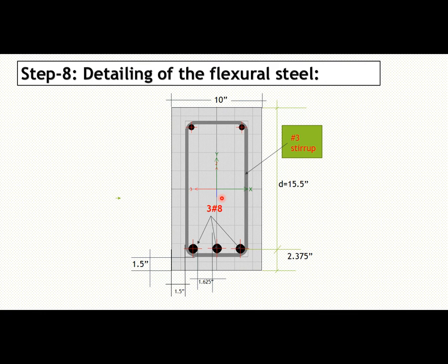Okay, if your beam becomes over reinforced, in an over reinforced beam section, the failure of the beam occurs by crushing of the concrete before yielding of the steel, which occurs suddenly, which is not expected. I hope that you have understood and your concept is clear now why we should design an under reinforced section.